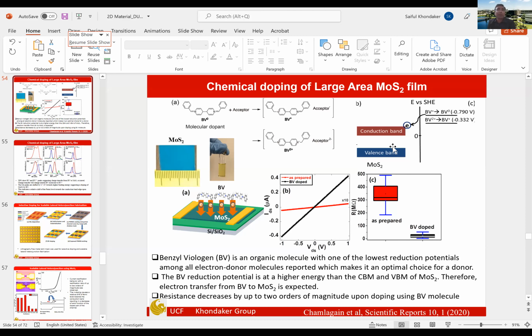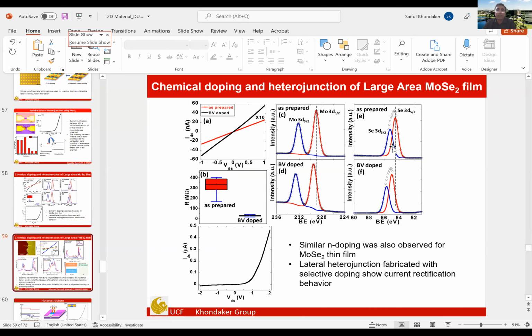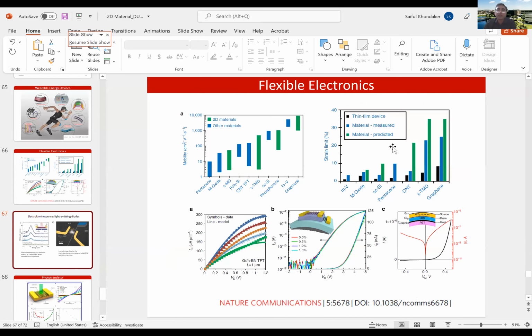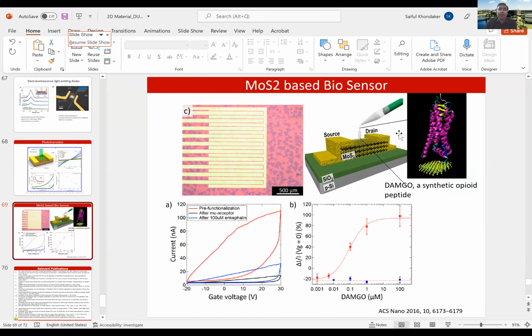There are many different sensing mechanisms, but I think in this particular case, the mechanism is that the material gives off electron. If I look at the current level, I will be able to tell whether it takes electron or gives off electron. So if I look at, okay, pure functionalization is the red one. Then after receptor, after harmonic, the current decreases. So the current decreases, it's actually hole doping. Okay, so it means that it is taking electron out of molybdenum disulfide. Okay, it's an acceptor molecule.